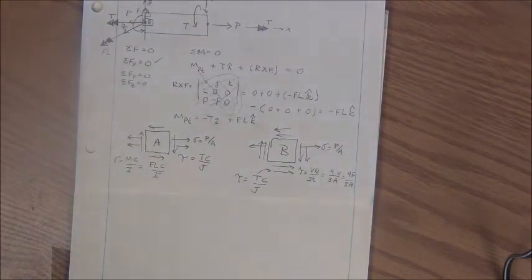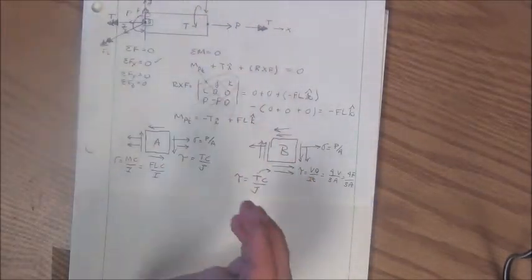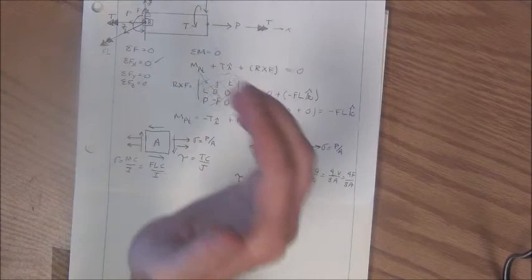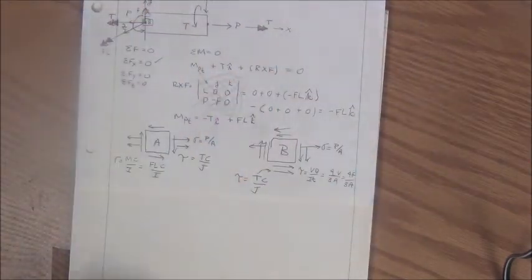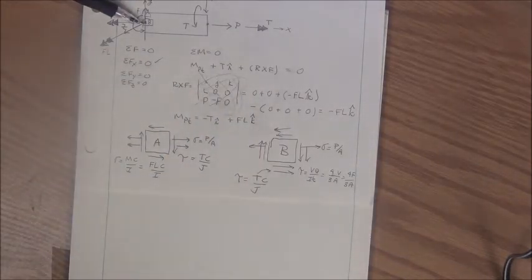The last load component to look at is this bending moment, and we realize that this bending moment is trying to bend my beam up, and B occurs at the centroid of that bend, and so it occurs at the neutral axis, and this bending moment FL will not cause any stress due to bending at location B because it's at the neutral axis.